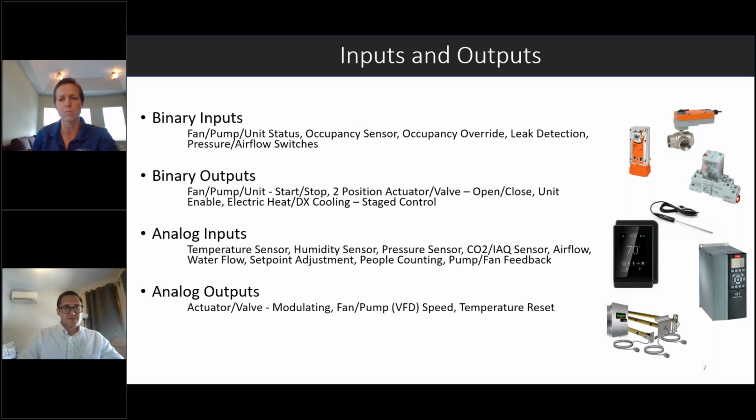Also on controllers, if you're looking at a cut sheet for a controller, you might see something like a universal output or universal input, and that means it can be configured to be either analog or binary. Yep. So that makes it a little bit easier for where you're landing points on a specific controller. With those universal points, you could land either analog or binary there. It's just easier in the field for wiring up a controller.